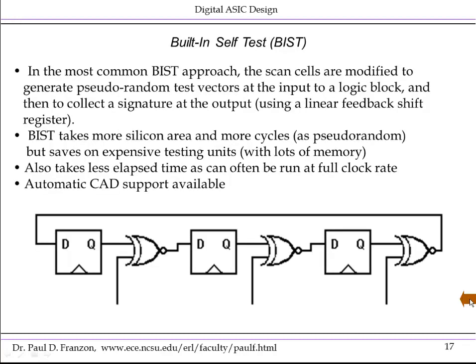In the rest of this section, we're going to deal with built-in self-test. This is conceptually a very attractive feature. Tell the chip, go forth and test thyself, and just tell me if you're good or not. If we could do that with a very low area overhead, it is very attractive. It saves all that headache of designing, of inserting scan chains and the tool path, working out where the scans are going, where they're not going, and generating all those vectors and compressing those vectors using expensive CAD tools, then applying those vectors using expensive test equipment.